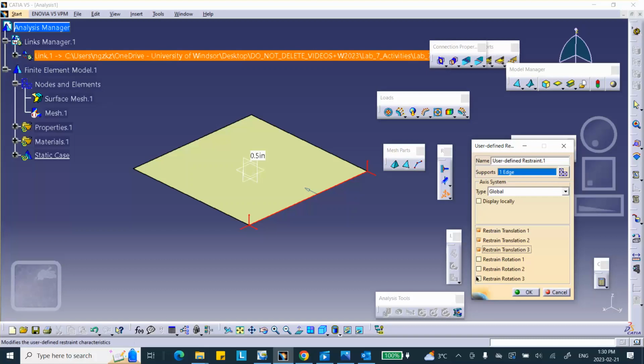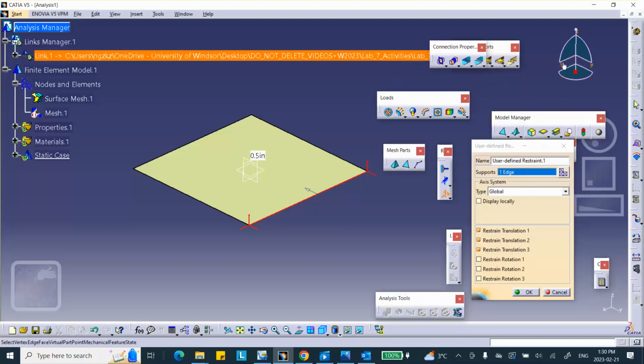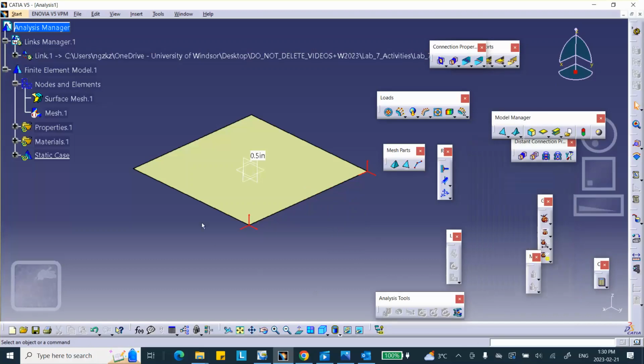And as far as rotations go, we know that there is no rotation about the x-axis because of the simple support, but I'm just going to leave the other ones alone. There may be no rotation in direction y and z because of the nature of the loading, but they're not fixed for sure. Okay, now this is in the plane of symmetry, so you look at that.